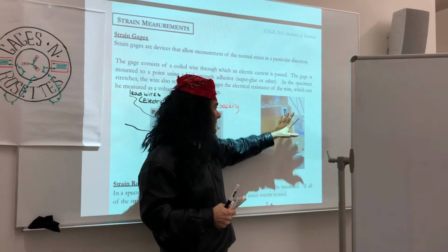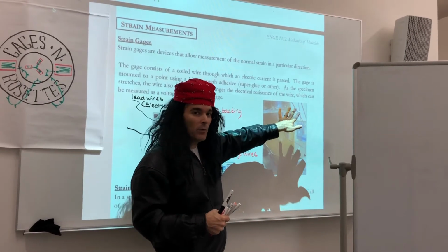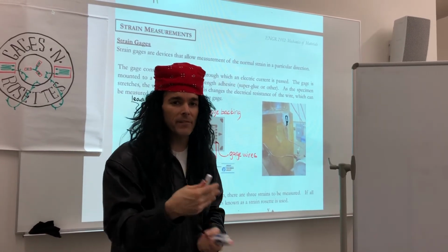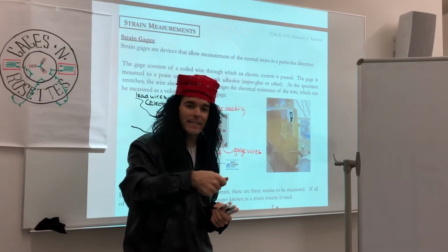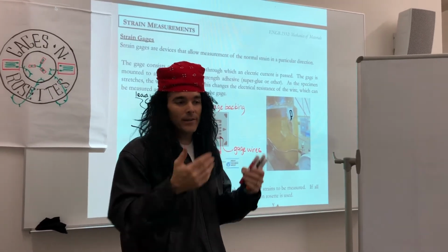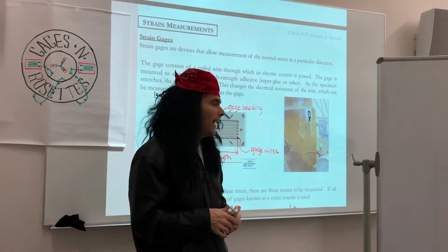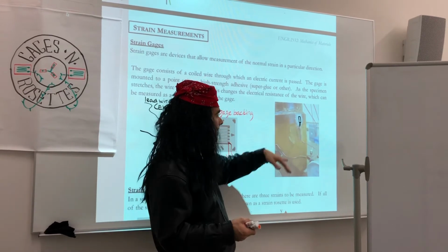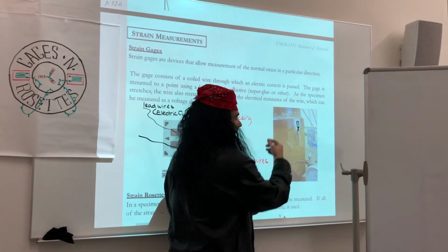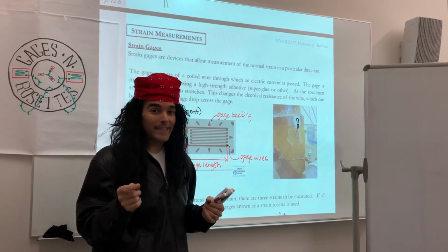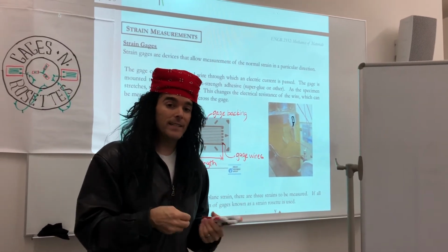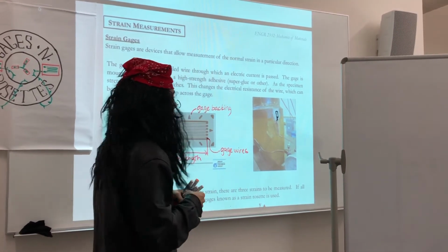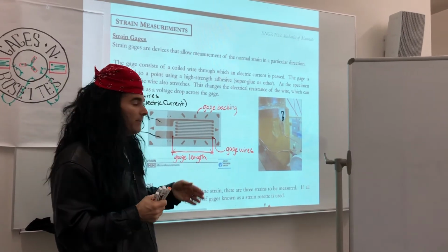So I wanted to find a normal strain, epsilon, in a particular direction. So I attached a gauge, and then I covered it up with wax here because we don't want to leave the surface exposed for too long if we're going to leave this up for days and days. If you're going to just attach the strain gauge and then use it pretty quickly or within a short period of time, it'll be okay. But I had this set up over weeks, so I wanted to prevent damage. So you just kind of cover it up. But we were pulling on this. I was able to measure the strains in my casting. I was able to compare that to the strains and the stresses I predicted in my computer model. All right, so that hopefully gives you a little bit of an idea of what strain gauges are.